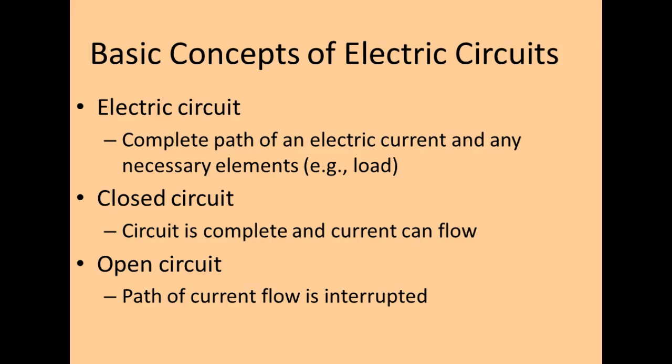So, the voltage. I got 230 here, don't I? That's considered voltage T, total voltage. And hopefully this is just a reminder of what you and Brian did in basic. How does the total voltage in this series circuit, what are the rules? Well, it's all additive. The voltage from 1 plus the voltage from 2 would equal the total. And so now these two share the voltage of 230.